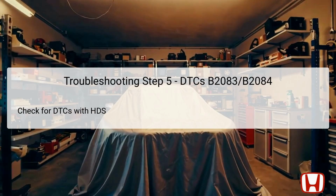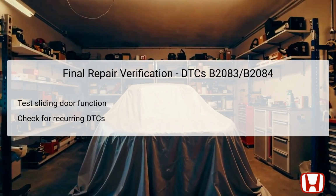Should no DTCs be indicated after the procedure, it suggests that the system is operating correctly and that any faults may have been intermittent or the components were restored to functionality. Continuous monitoring may be recommended to verify the system's stability moving forward. After all troubleshooting steps are completed, the next stage is to verify if repairs have been successful.